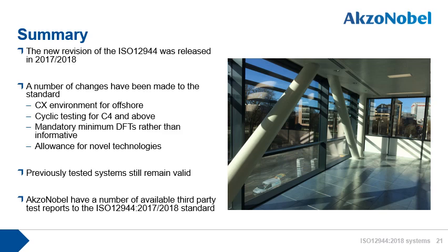Minimum DFTs are now mandatory minimums rather than informative as was the case previously. The standard also does make allowances for innovative or novel technologies that may differ in the chemical composition or DFTs from what is prescribed in the standard.